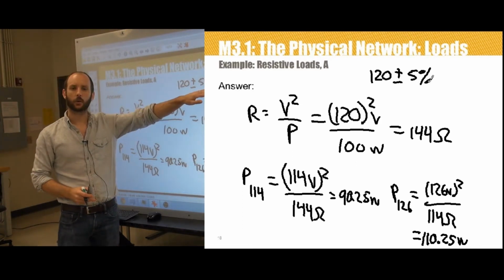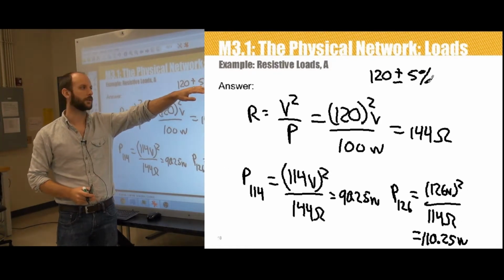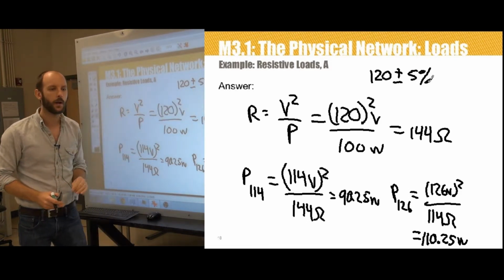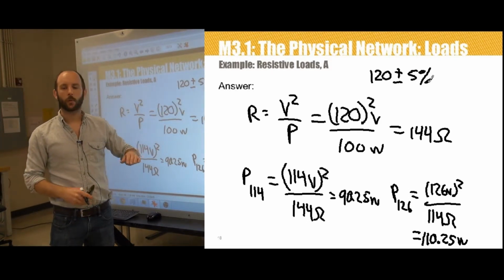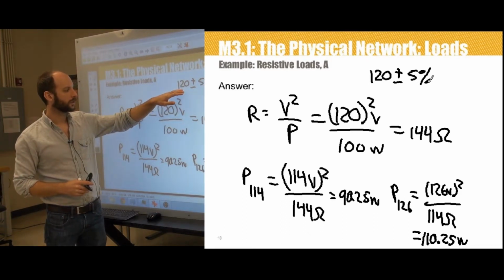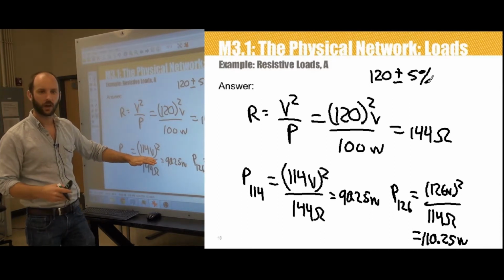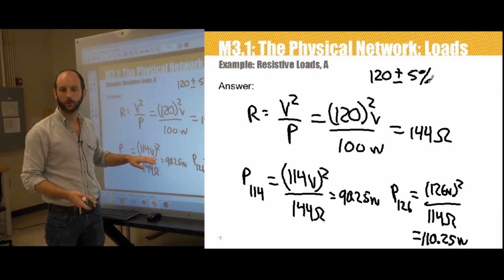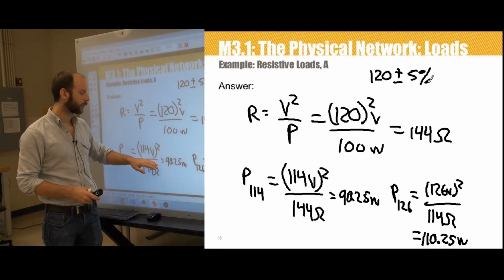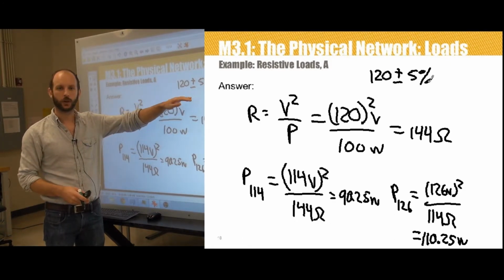Some industries actually require much higher voltage sensitivities for their equipment, plus or minus 0.1%. The semiconductor industry comes to mind. From a residential level, what system planners have noticed is, what if we could get everybody to operate at 114 volts? Appliances are rated for 114 volts. When they're tested and designed by the engineers who build appliances, they have to run off 114 volts RMS because it's part of the US voltage standard tolerance.